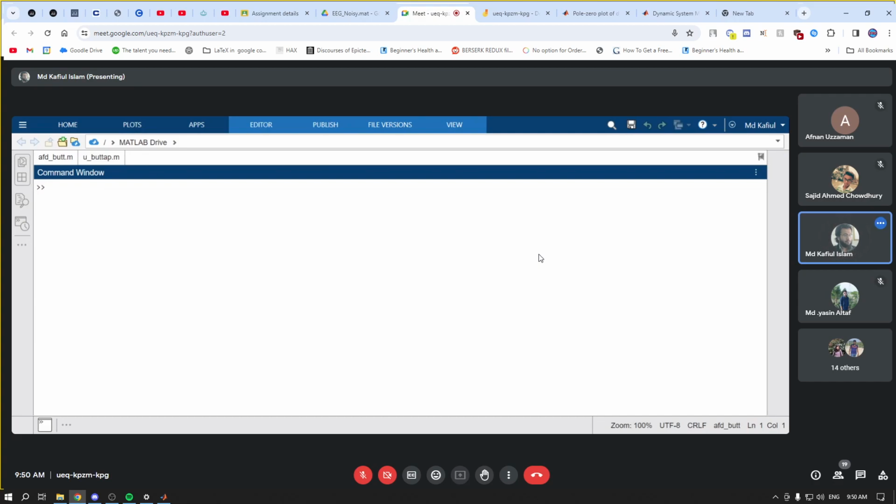One of them is depth of knowledge, the depth of analysis that you are going to do. There are also some conflicting requirements you will find. For example, we have seen the conflicting requirement while choosing the window function. Remember, there was minimum stop band attenuation AS and there was transition bandwidth. If I get a better result in terms of transition bandwidth, then I lose in terms of stop band attenuation.